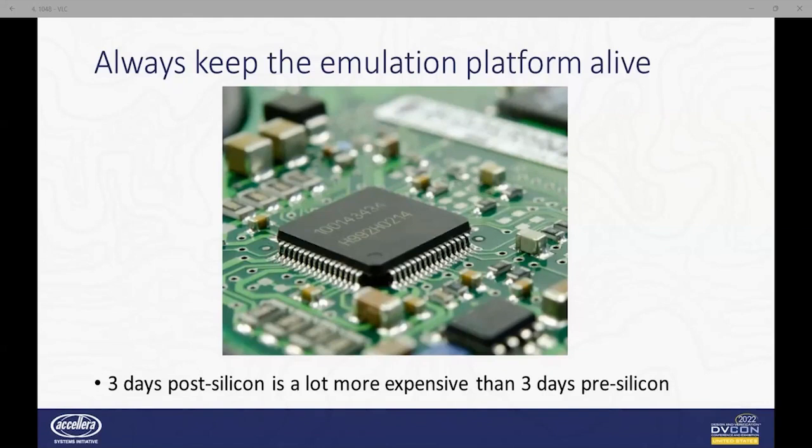If the problem can be reproduced in emulation, it is a digital problem. Just follow the previous steps to root cause the issue. If the problem is not reproducible, it is very likely an analog, timing, or yield problem.